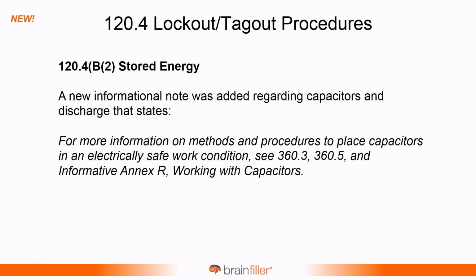For lockout tagout, there are also requirements about stored energy. There was a new addition that references, for more information on methods and procedures to place capacitors in an electrically safe work condition, a new annex and a new article. So Article 360 and Annex R were both added, and those deal directly with capacitor safety. And they're both quite large articles.